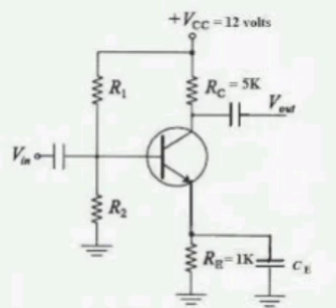Time period T0 equal to T high plus T low. T0 equal to 138 microseconds. Frequency of output is F0 equal to 1 by T0, that equals 7.246 kilohertz. Duty cycle of output equal to T high by T0 into 100%, that equals 69 by 138 into 100%, that equals 50%.